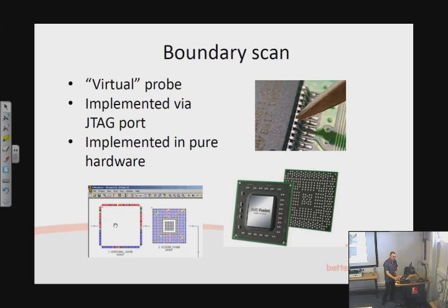And so yes, you can see what we're trying to do here is create a capability and yet another PC-based tool to effectively measure highs and lows and check continuity generally, to check that the chip has been soldered down properly and the signals have been passed to it correctly. So the closest thing we can get to putting an oscilloscope, well, more like a logic analyzer to be honest, because it's generally only got high-low resolution. But a good workaround to this ball grid array problem.